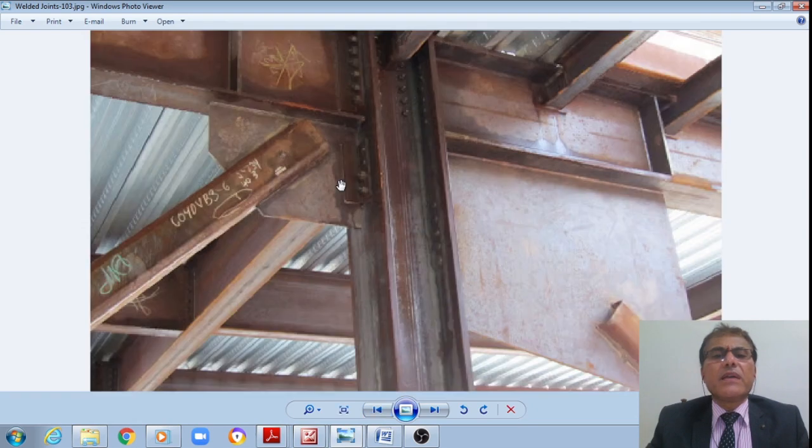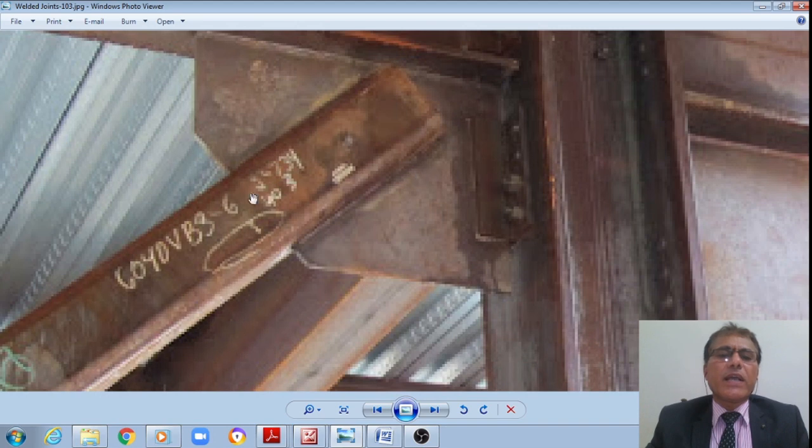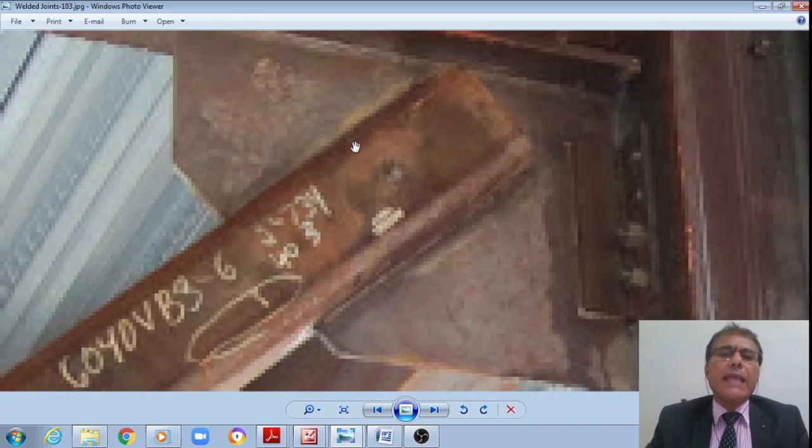Yes, right? This overlap we have just seen is actually connected to a gusset plate, a channel actually. It is not an angle, student. This is a channel that I am showing, right? That is how the overlap is required at the top. Just now we got 225 mm, and at the bottom just 115 mm, right?